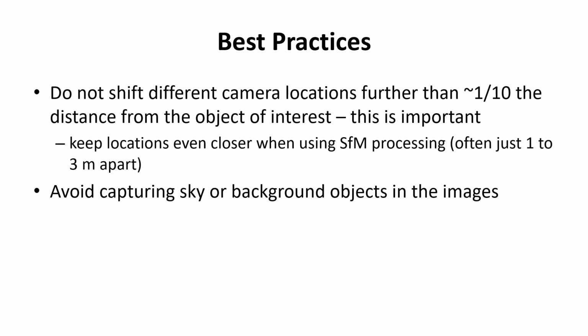Don't shift your camera stations too far apart. As I said, about 1/10 of the distance that you are away from the object. And I add the note, this is important. People that are new to photogrammetry will tend to walk far too long a distance before they take their next photograph. You only need, in many cases, 2 or 3 steps. Then you take your next photograph.